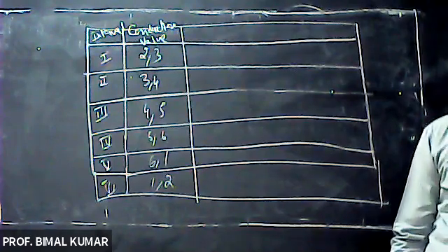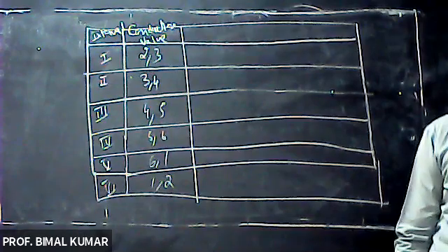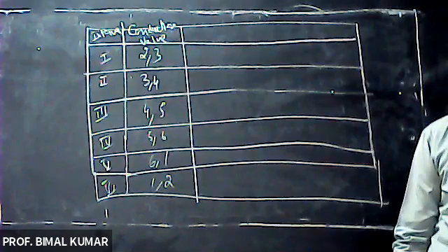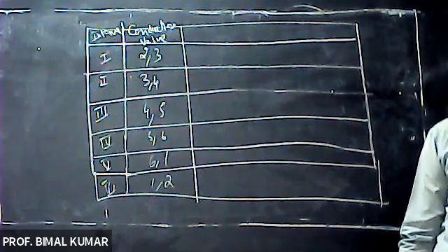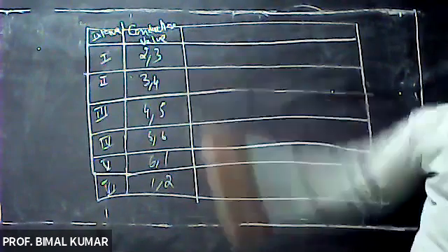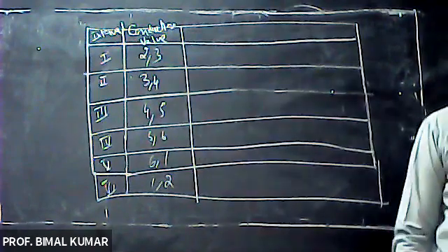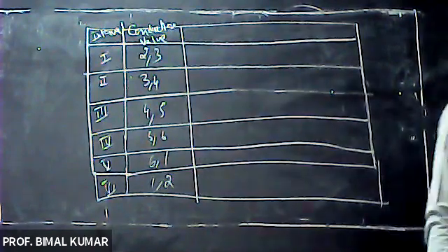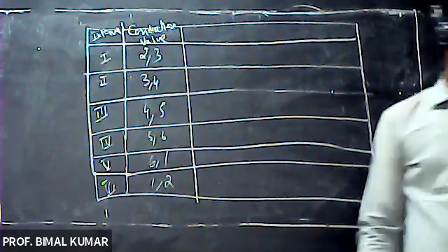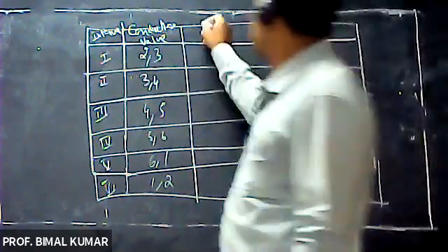During the first interval, thyristors 2 and 3 will conduct. Then during the second interval, 3 and 4 will conduct. Then 4 and 5, 5 and 6, 6 and 1 will conduct, and during the last, 1 and 2. And again after this, your cycle is going to repeat. Right? So after that, DC voltage.